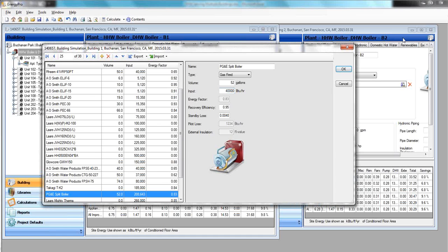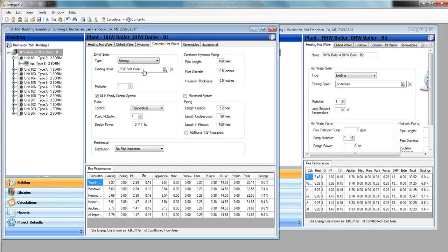40,000 BTUs, then you'll see how the standby loss now is going away. It's less than 75,000. So 75,001 brings the standby loss calculation back in. Hopefully that'll clear that up. It's basically that 75,000 BTU threshold, equal to or less than, greater than, that kind of thing. Yep, perfect. That was great. Thank you for showing it like that. I think that cleared it up.